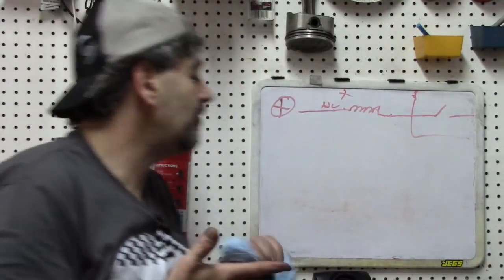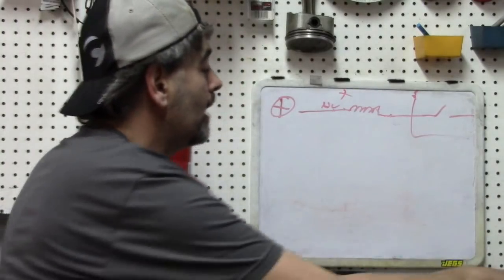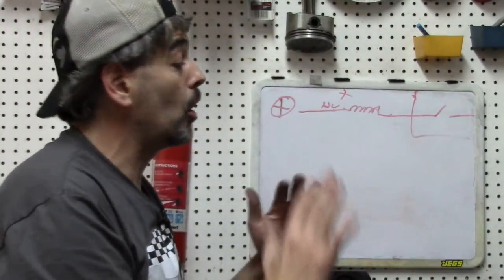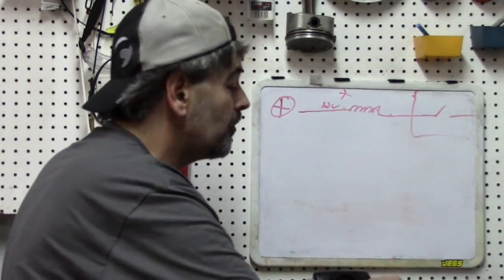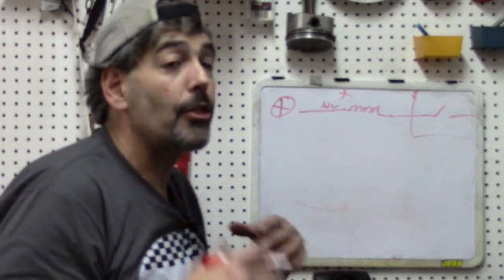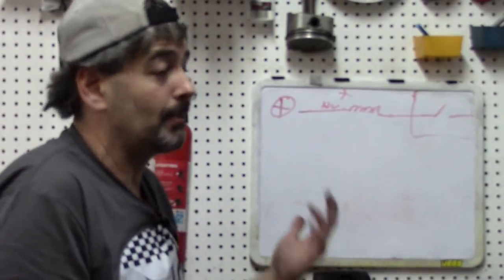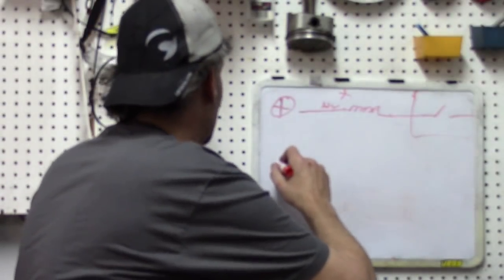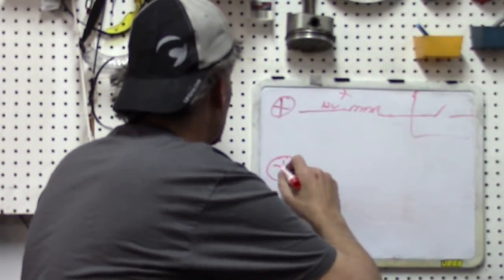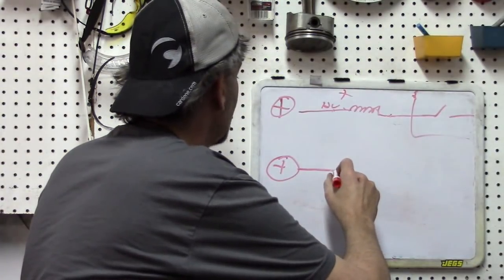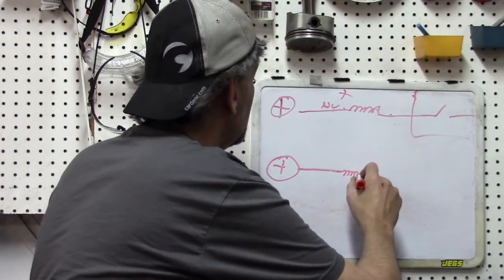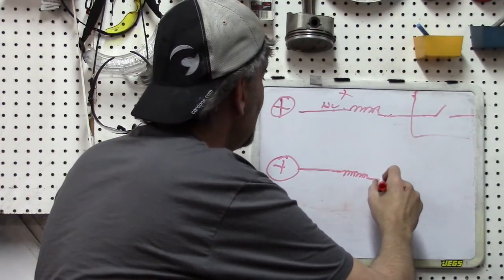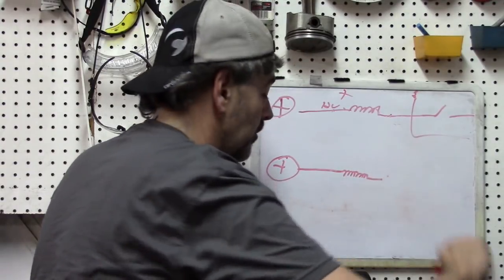Okay, let's see if you were right, and hopefully you're able to figure this out on your own if you thought about it and drew it out and used your skills. So we're going to do this on a 3 wire, same thing on a 4 wire, but just simpler to draw the 3 wire, obviously. And we're going to make this very simple. We've got our battery positive. We're going to the coil, okay? And then we've got our transistor control.